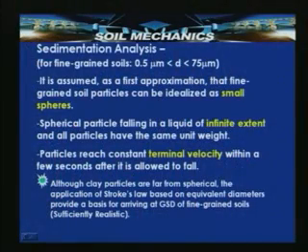So, as a first approximation, we assume that all the fine grained soil particles are idealized as small spheres, a spherical particle falling in a liquid of infinite extent, and all particles have the same unit weight. We are also assuming that particles reach a constant terminal velocity within a few seconds after being allowed to fall.